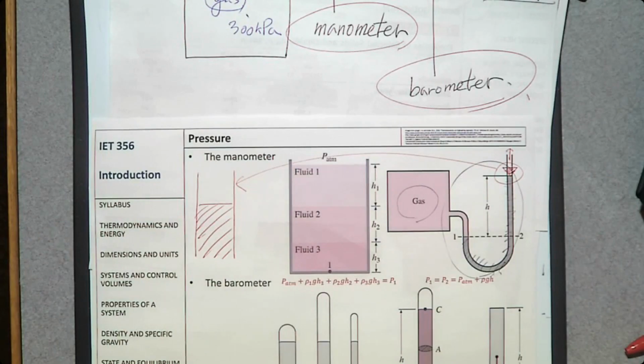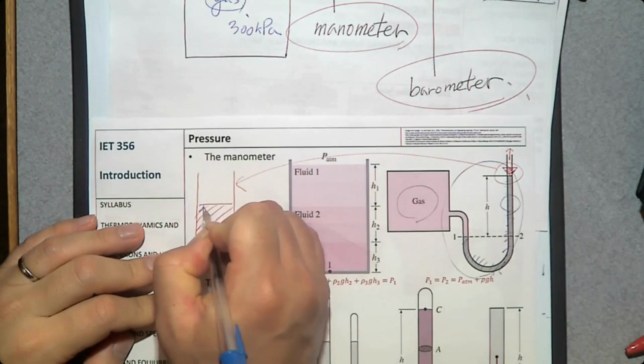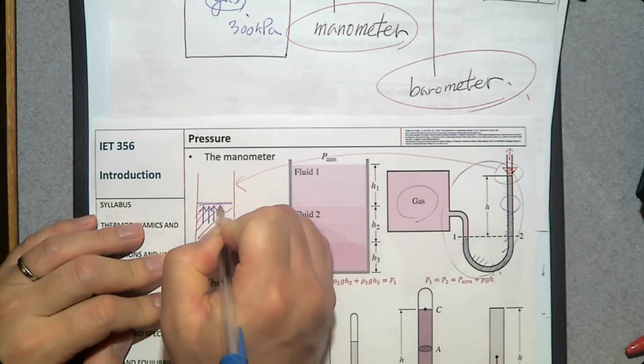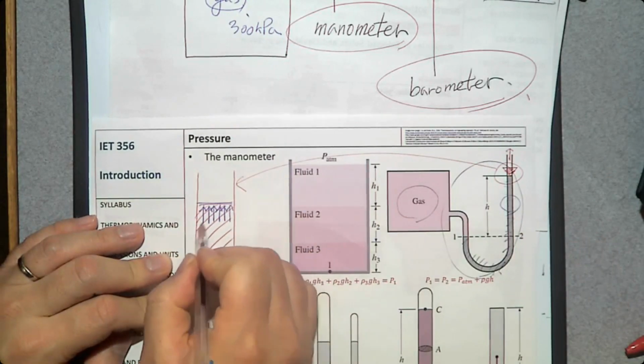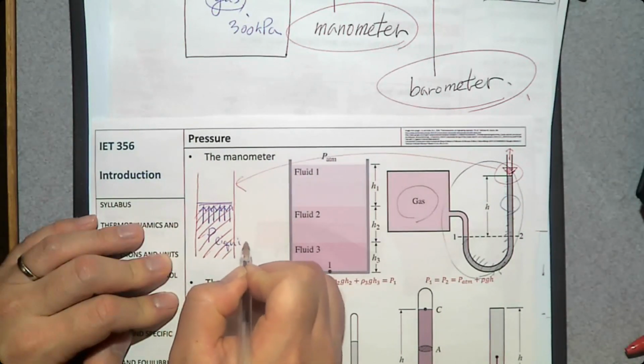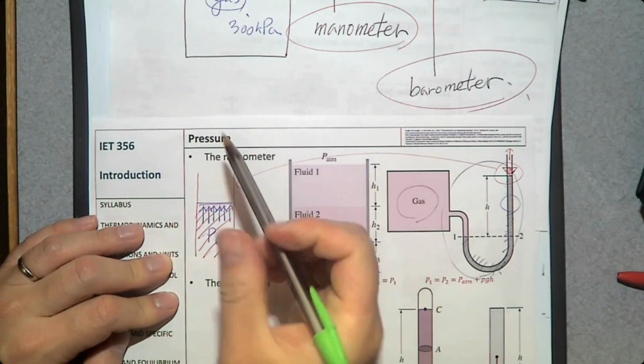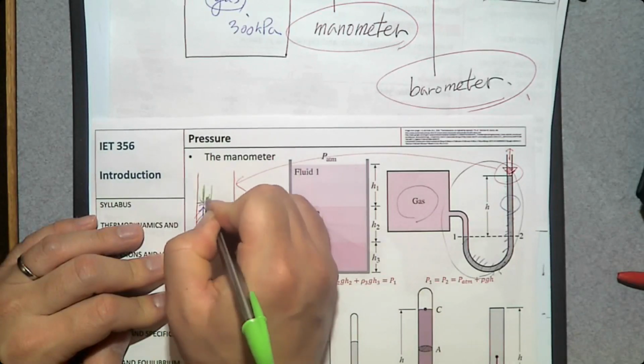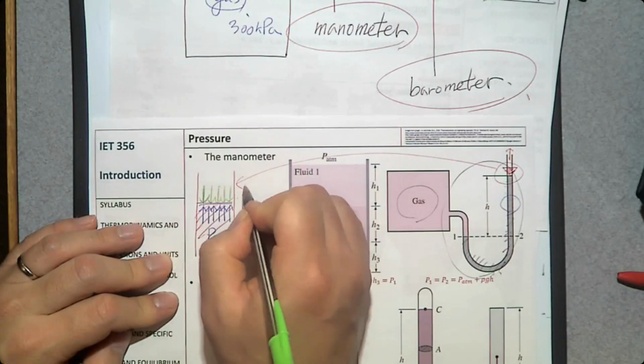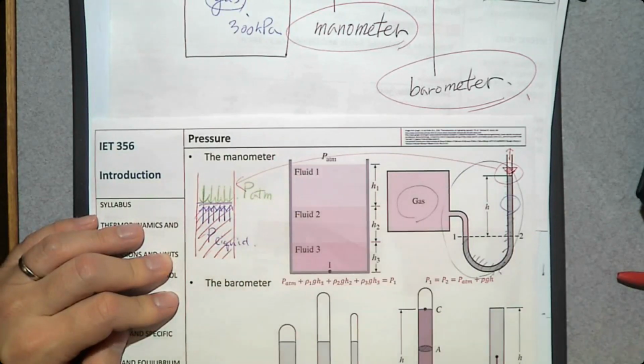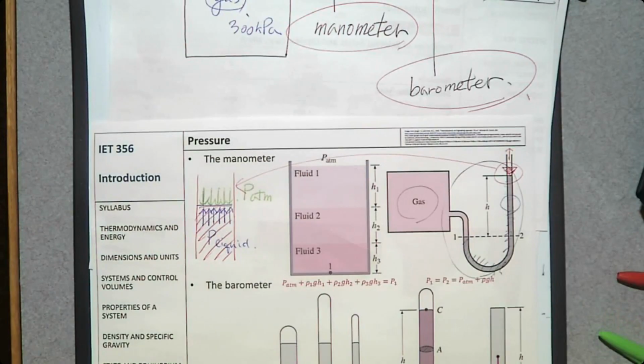There is pressure by this liquid onto this interface in this direction. So this is the pressure by the liquid inside. And what else? There's a pressure by the atmosphere, P_ATM. If liquid pressure is greater than air pressure, what happens? The interface moves upward until the pressures are equal.